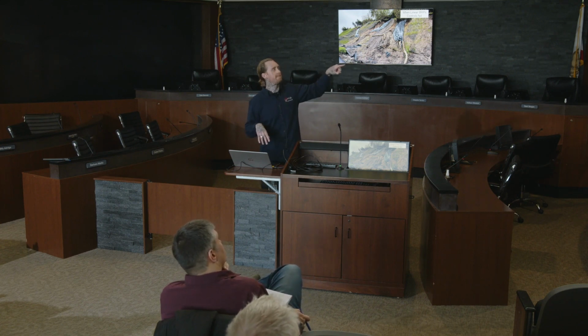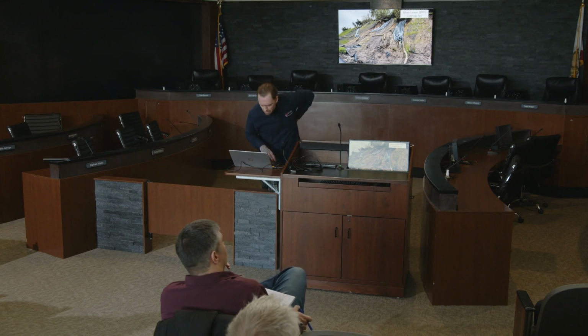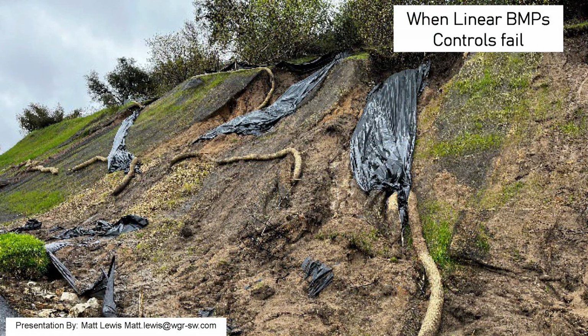With this, and you would have to get into the math, but I believe that it should have been probably every 4 feet, give or take, when it came to that linear break. And if I'm not mistaken, those linear breaks were not keyed in. You can kind of tell further down that they're just staked in. They're not keyed in, right? A little trench wasn't built and they weren't set into place properly.